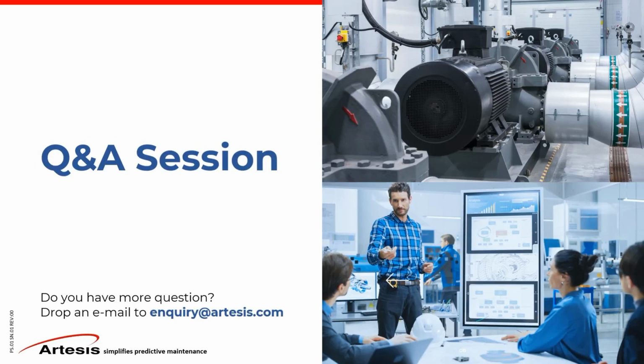I meant with devices, how can we monitor and improve the harmonics generated from the drives or the motors themselves? Of course, this has to do with the filtering, right? You have to have active or passive filtering. So this system will tell you that there's the problem. The solution to that will vary depending on the application. But for harmonics, of course, the active filtering is the first one that comes to mind.